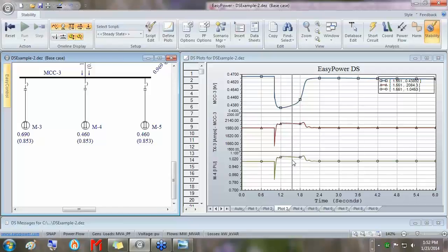Go ahead, do the best you can on gathering information and data. Yes, and put the data in all those other models for all the other motors so that when you're starting the one, you get the effect of all the others because your voltage will go lower because of the dynamic effects of those other motors as they draw more current during the voltage depression.